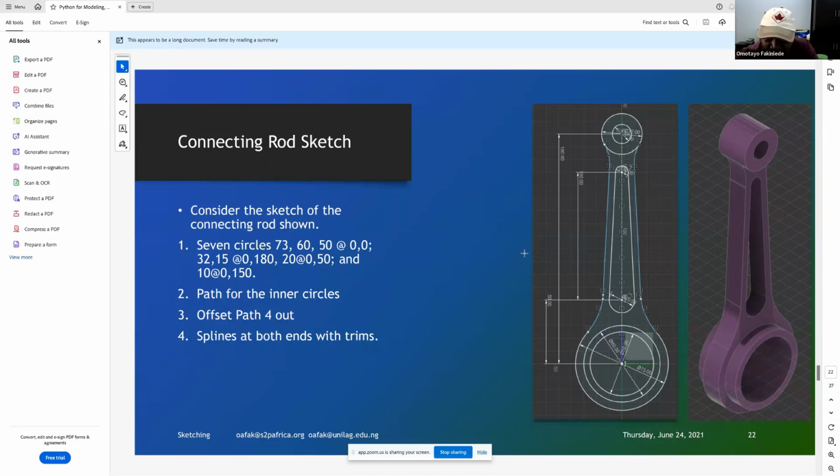And then you can do a path, and then you can trim, you can cut off unnecessary parts. Let us say you draw a line and the line is too much. You can trim off the excess line, and you can have another line cutting it. And then you can do construction lines. We will see how we get a line and turn it to a construction line.